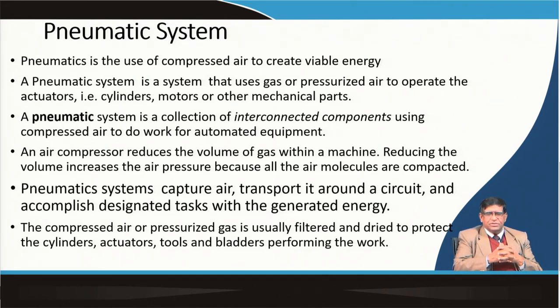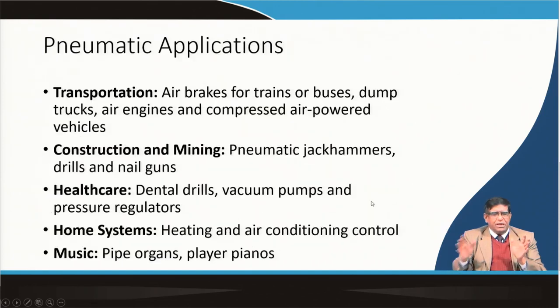So, this pressurized air will have to be used in the system, so it will have to be filtered so that no dust or other corrosive particles go into the components, and it also needs to be dried so that water droplets do not go inside the components of the circuit. Sometimes you will also have to use some additives in that air, so that corrosion or other problems do not happen. So, that way you will have to protect the system by keeping the air clean. So, these are the basic things in a system.